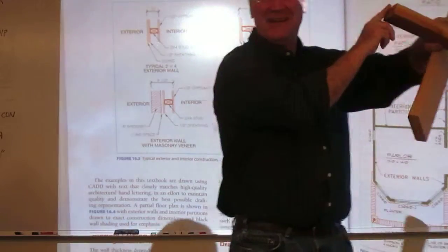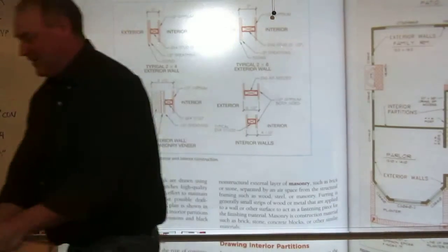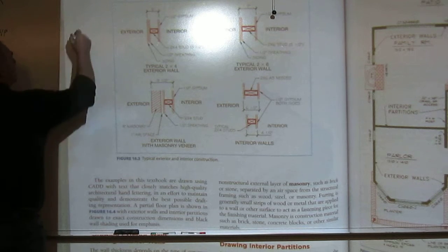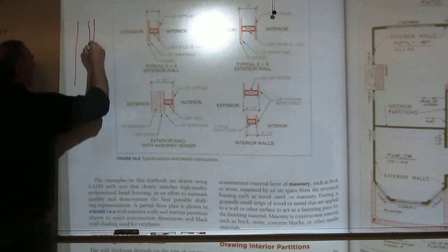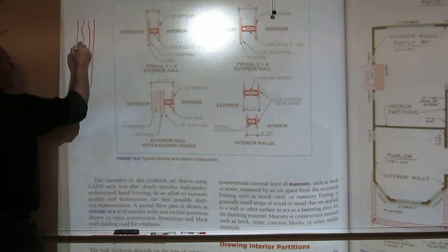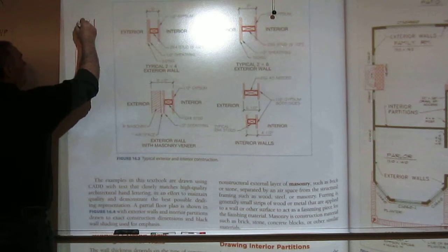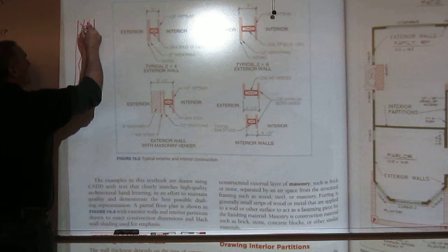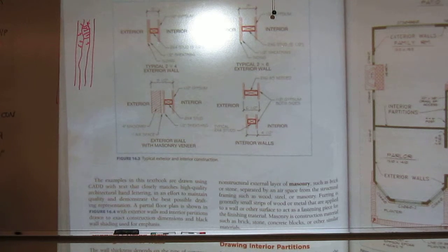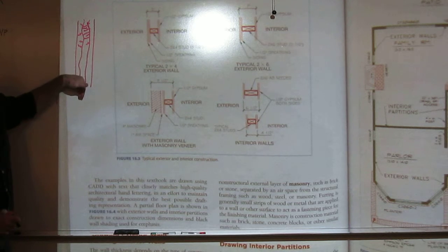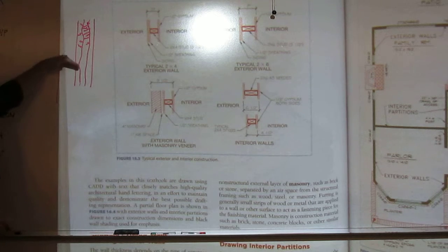Grain, right? Wood grain. If you look at a piece of wood under a microscope, it's really a pretty fascinating product. So if I've got a piece of wood and I've got grain in it, as the tree grows, it has millions of little fibers that feed in between these layers, back and forth. And that's really where your strength comes from. Now, it comes from there if your forces are working parallel to the grain. If we work perpendicular to that grain, that strength is not there.